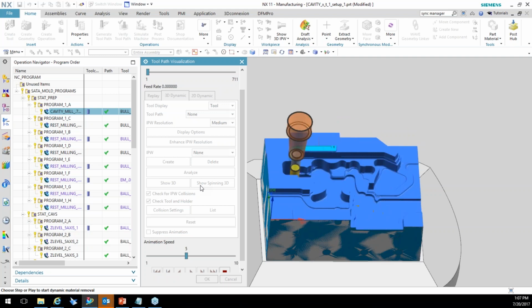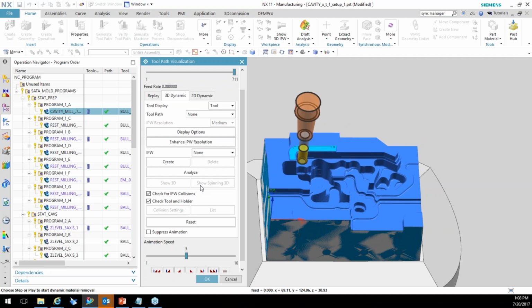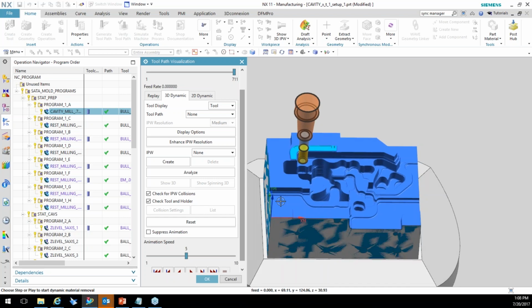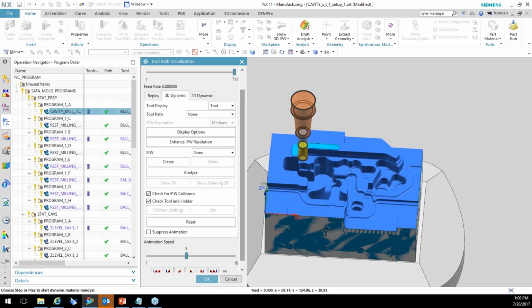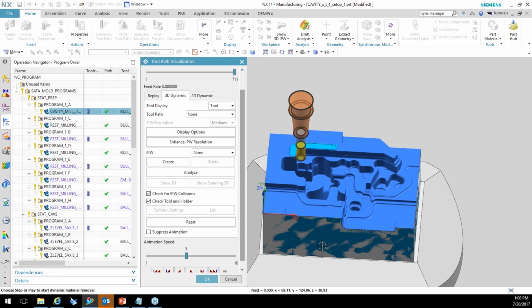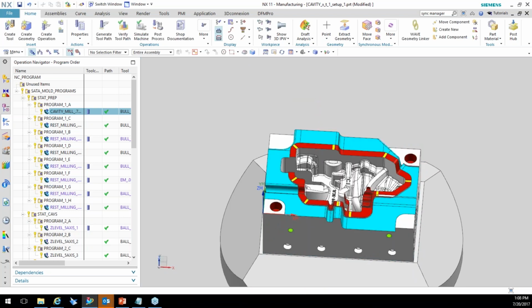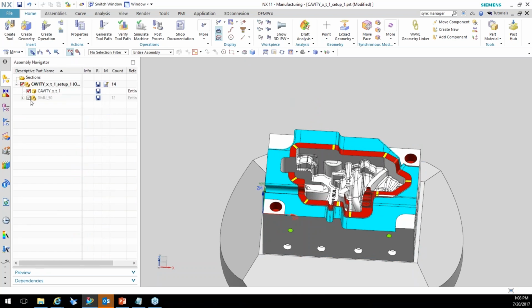And when you are doing multi-axis machines, simulations with synchronization, you have to have the G-code driven simulation because that's the only way to get to the synchronization manager. So you can see that the material removal and verification will suffice for most of your applications until you get to 4 and 5-axis or multi-axis work. So now let's go and turn the machine tool on.